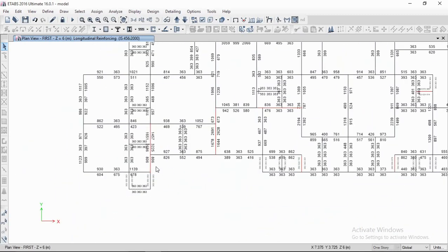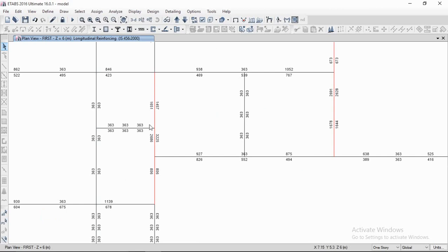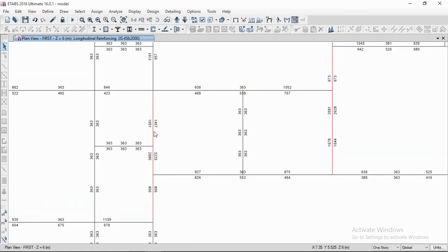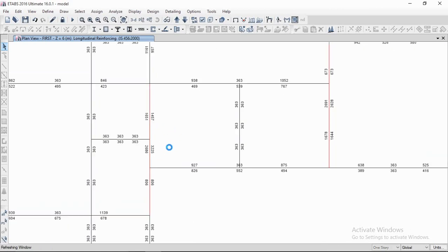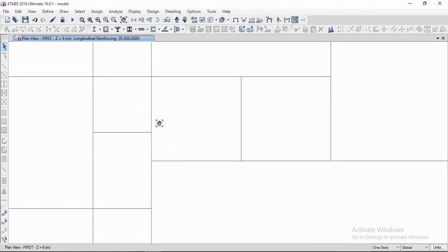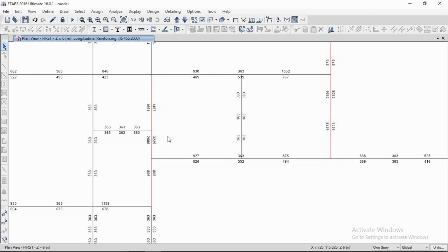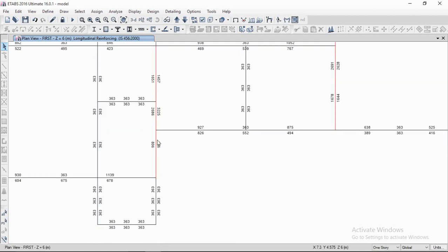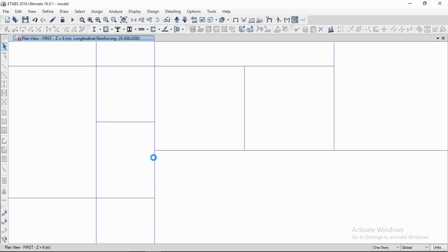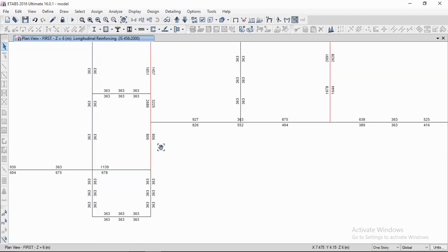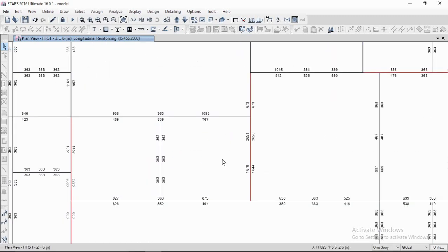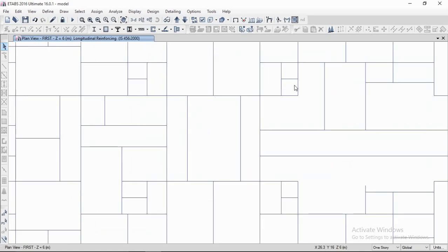In this case, when the beam does not pass for any section, we have to check how much depth you can increase as per the specification of the building, that is the lintel level, or how much width you can increase with respect to your column width.